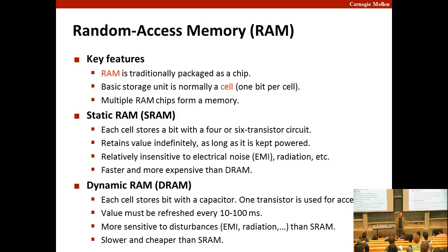Beyond that, the circuitry for faster memory is harder to build. Beyond that, registers can be faster because there's no addressing problem. Right? I have 16 registers. It's much easier to address. I don't need very many address lines, right? If I have way more memory, now I start to need a lot of address lines to address that memory. And now I need to be able to deal with that in terms of the circuit that addresses the memory.